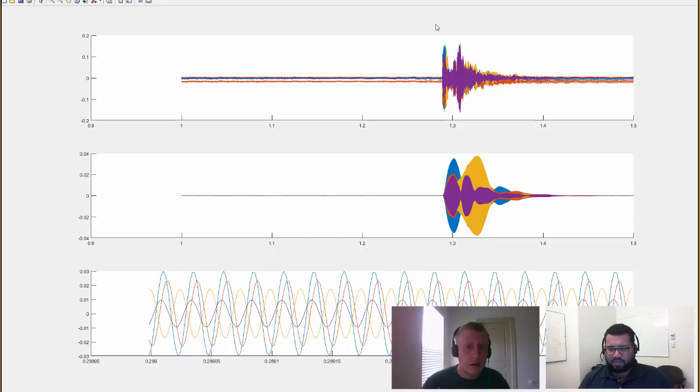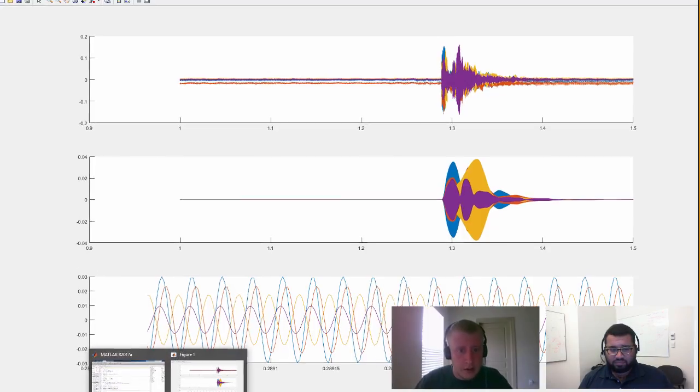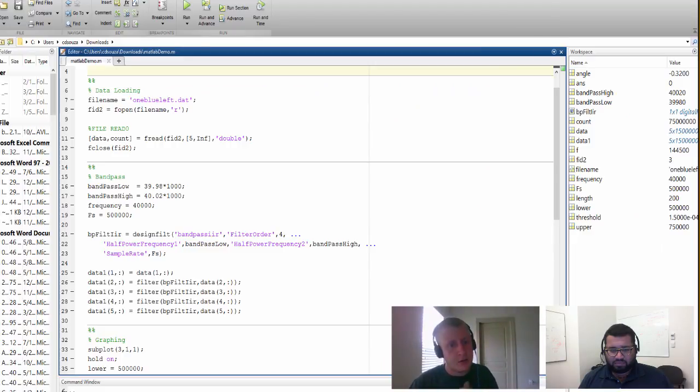So to find that front of the waveform, first step obviously is filter. We've got to get rid of the noise in this, and what we're going to do is take it through a bandpass, and that's what is going to leave you with this middle plot here. And to do that, what we do in MATLAB is we design a filter. The sound sample we have here, which we've loaded in, is a test sample that we took in our university pool. It's a 40 kilohertz sound sample, and we're just going to start by designing a filter to work around that and filter that data. So we pick a small band above and below that 40 kilohertz target.